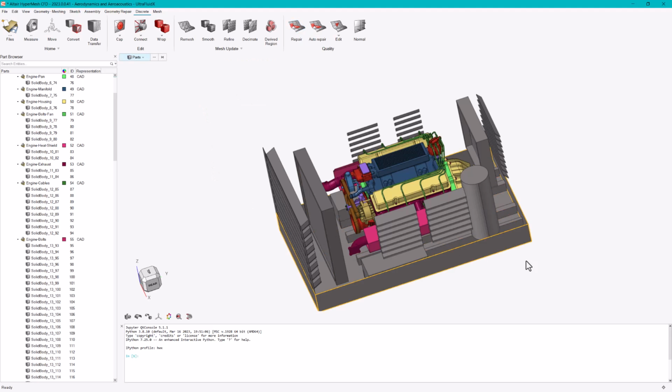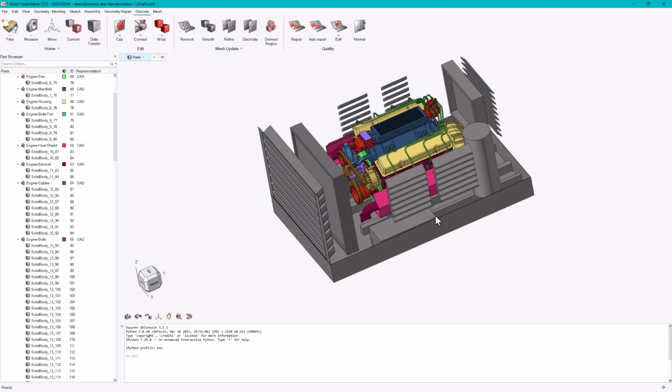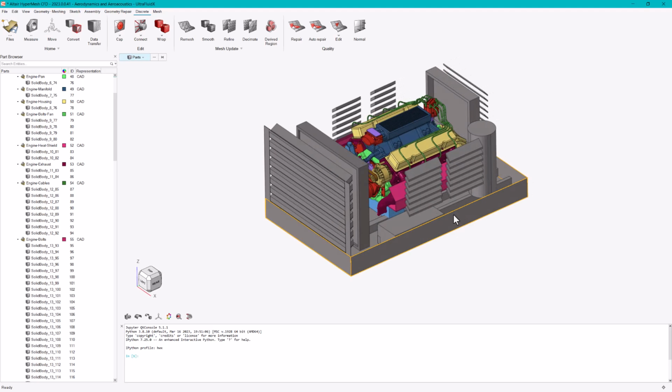In some situations, we will need to wrap the mesh, as I mentioned at the beginning of this tutorial. If the part has very large internal volume that is not part of the interest of this flow simulation, or if the part has large number of elements and it is not a flow critical part, then we prefer to wrap the mesh.